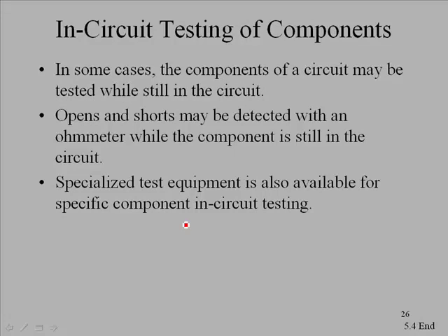In-circuit testing of components. This is the idea that sometimes you can test components while they're in the circuit. In some cases, the components of a circuit may be tested while still in the circuit. Opens and shorts may be detected with an ohmmeter while the component is still in the circuit. Specialized test equipment is also available for specific component in-circuit testing, and this is a common practice where you actually measure the